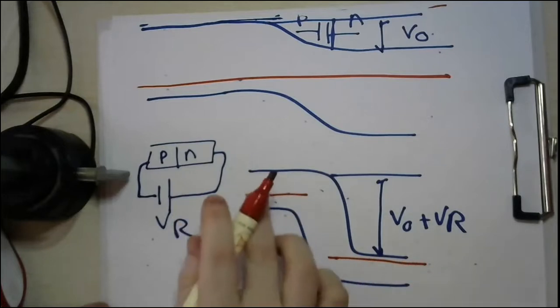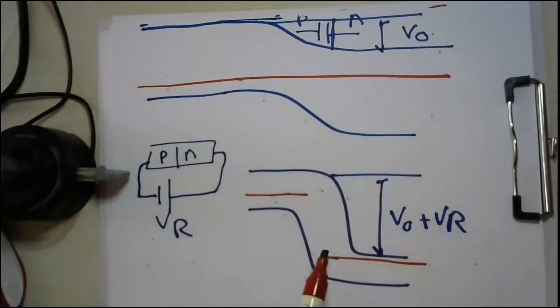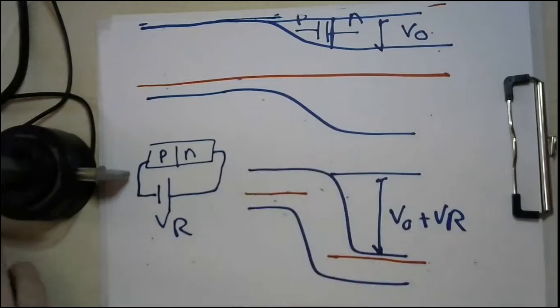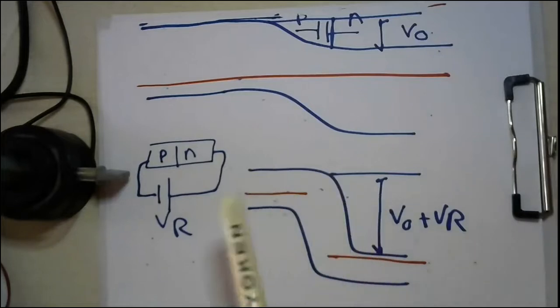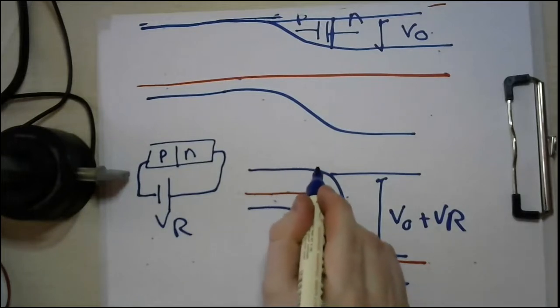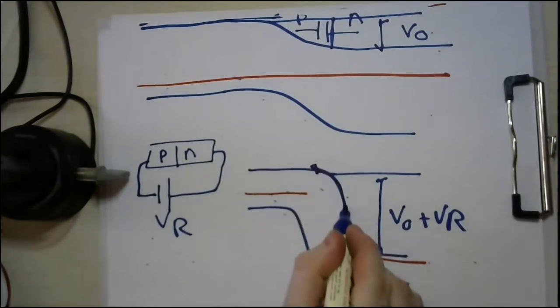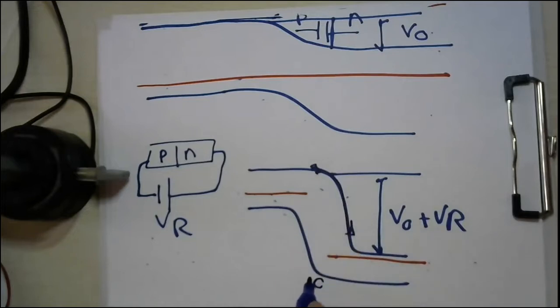You have now a split Fermi level, no longer a flat Fermi level, because this energy band diagram is no longer under equilibrium. So simply what I did is that we add the voltages. Okay, so as you can see here, my dear students, we are just increasing the total potential. That's why the height of these barriers has increased. After the increase of this height, you will find that more electrons will drift here and more holes will drift there.